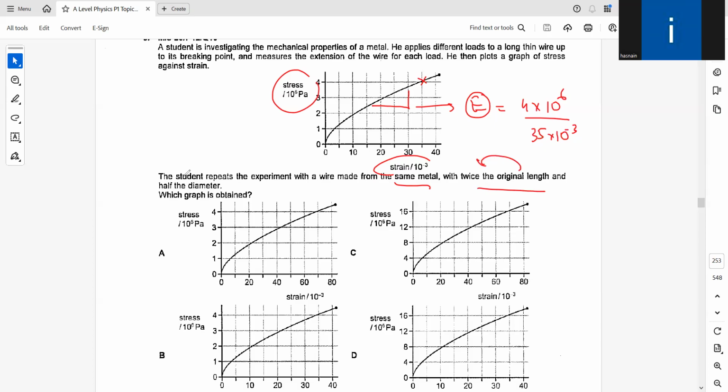Why? Because spring constant is something that can change with changing the diameter of the spring, changing the length of the spring. So that is dependent upon the dimensions originally. But Young's modulus was derived in this manner so as to have a constant of material, not on dimension. So if Young's modulus is there, that means regardless of the length of the pipe or the material or the diameter of the rod, it has to have the same Young's modulus.